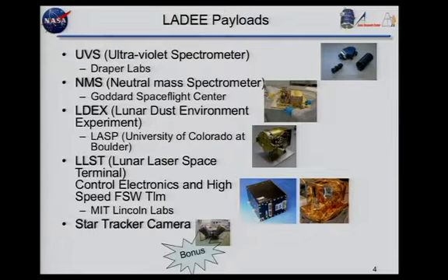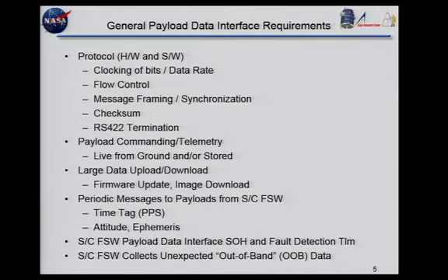But I wouldn't say it was an afterthought, because within the flight software, people were saying there's a camera on there, we should make sure there's an ability to get the images down from it when we were designing the interface for the star tracker. This is a case where, if you're just doing strictly what the requirements called for, we would never have been able to take pictures, because the requirements just called for getting the quaternion off of the star tracker and sending a time tag to it so we could sync up our times.